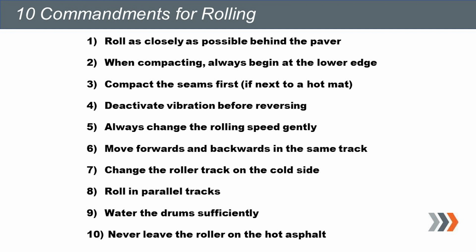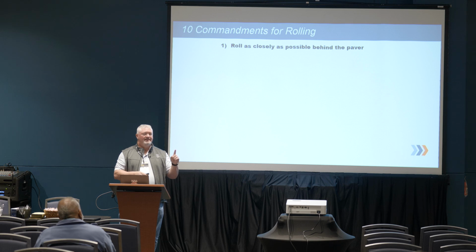All right, 10 commandments of rolling. Roll as close as possible to the paver, but do not hit the paver.